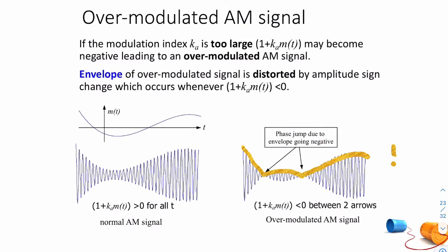Now remember, we said the modulation index should always be greater than 0 and less than or equal to 1. If the modulation index ever exceeds 1, we end up with something called overmodulated AM. So that's when M is greater than 1. Undermodulation, remember, wasn't a big problem, but overmodulation is a problem. And the reason, as you can see, is we can no longer recover the message by tracing the envelope.